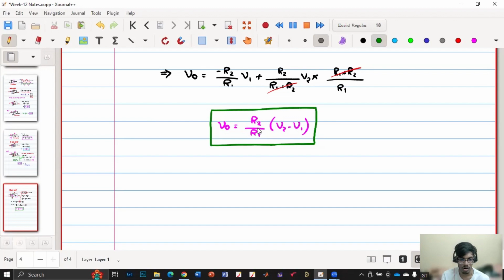So I consider the cost and also the availability of the resistor. Maybe 100K is not available at that time. Then I'll not choose 100K. If say 20K and 2K are available, I'll consider 2K and 20K. So my main objective is to get the amplification.